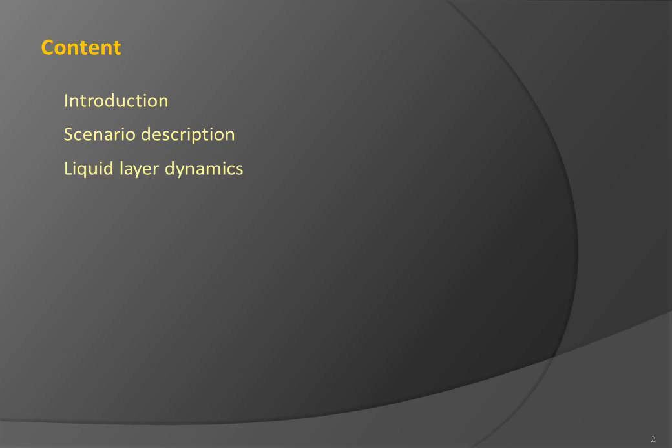Dynamics of the LNG layer deserves special attention as it determines the initial distribution of the LNG. We will discuss modeling approximations of the LNG source, that is the impingement point onto the water surface, spreading of the LNG liquid layer, and exchange between the LNG liquid layer and the ambient, that is gaseous environment. Low temperature of the stored LNG leads to boiling at its release, and at favorable condition even to rapid phase transition. The associated regimes, that is film boiling, transition boiling, rapid phase transition, and nucleate boiling, will be presented in detail in the next section.